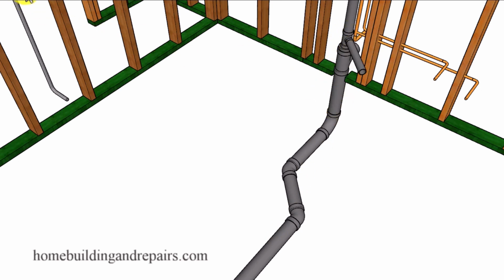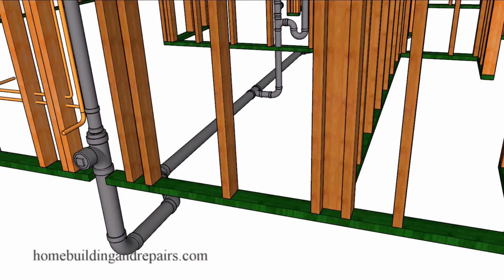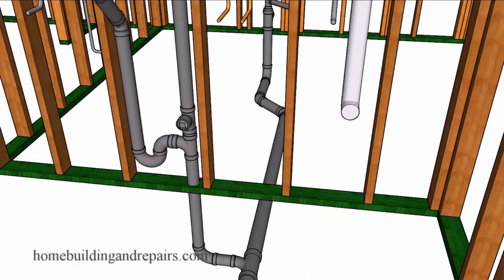And like I said, if it's easier for you to just simply unscrew the clean out on the outside and run a snake through here, then do that first. If not, take a look at the kitchen sink trap. And a good clue, if you do remove the clean out cover and no water comes out, then there's a good chance the kitchen trap is clogged. If water does come out, then there's a good chance the drain is clogged. So be careful whenever you're opening a clean out inside, because you could get a lot of water coming out of it.